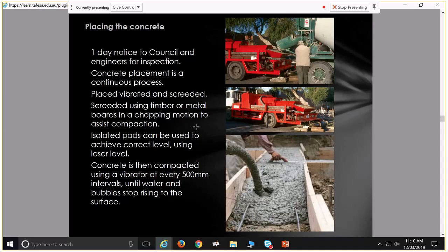Exactly, yes. I know, I'm just swearing at you because it's way against the rules. It is way against the rules because when you add water, yes, you make it weak, but also if your concrete has started to go off, if that chemical reaction has happened, and then you're adding water and you're still agitating it, breaking it apart, you're not going to get anywhere near the same sort of bond.